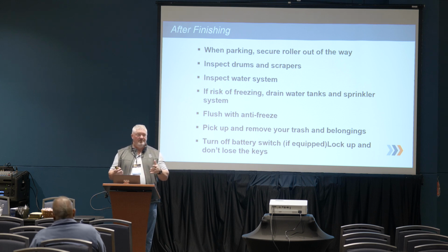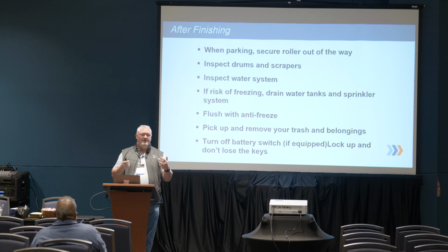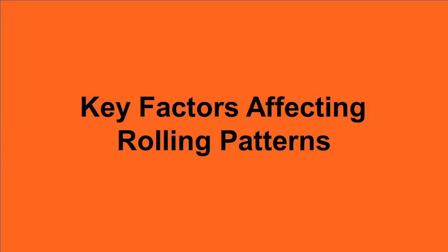The newer machines now, because we have the DEF fluid, when you shut the machine off, the pump runs from the DEF fluid to pull all that material through the lines back into the pump. If you disrupt that and it gets clogged, the machines are going to derate and you're going to have a machine that you can't use. And it creates a lot more problems after that.